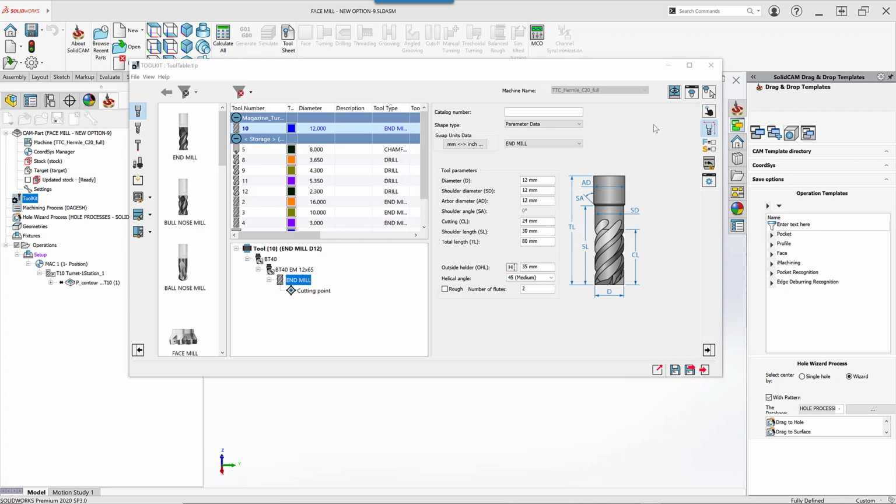Now let's go to the icons that we have on our right hand side. You'll note at this moment the icon for the topology is pressed. That's because we are on our end mill, and our default on the actual tool itself is the topology of the tool. In the topology of the tool, since I'm here already, we have all the necessary information for defining the actual shape of our tool, whether it be diameter, changing it, right-clicking inside it.